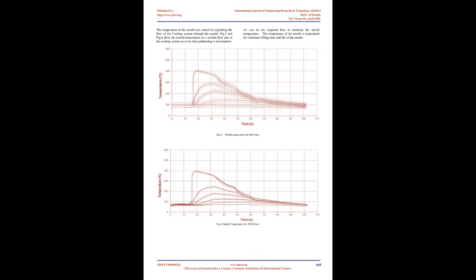4. Development of preheating temperature equation for HPDC. A significant precondition for the production of high-quality castings is keeping an optimal temperature of the respective parts of the mold cavity surface. This temperature depends on the temperature of the material, the quantity of the metal, the method of cooling of the casting mold, the thermal conductivity of the mold material and the time during which the casting remains in the mold. The following applies for the thermal balance per one cycle.